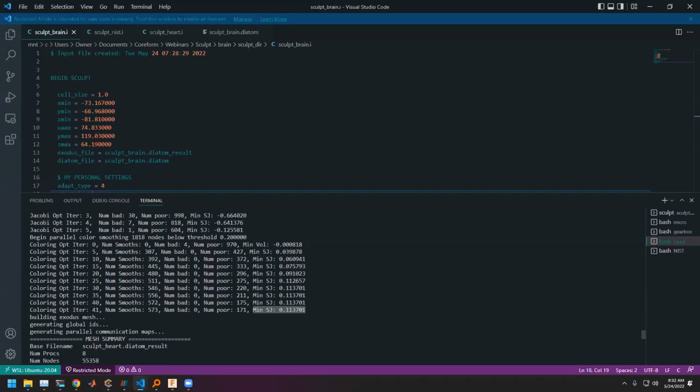But if you do have cases where you have those large differences, it may occur that Sculpt might miss those small features that branch off. If that's the case, then I would recommend using a denser or finer initial mesh. But that is a good general application for Sculpt, these biological or organic shapes. Great.